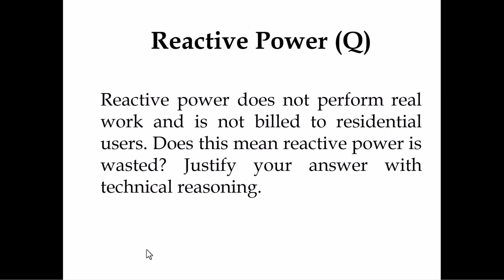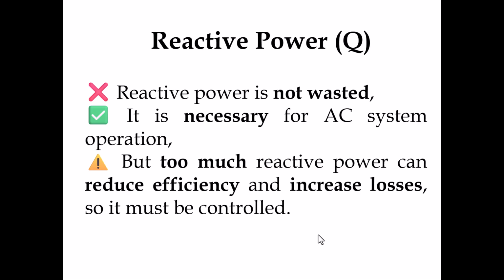Actually, reactive power is not wasted, but it must be managed. Reactive power does not result in net energy transferred to the load, as I discussed earlier. Instead, it is cyclically exchanged between the source and the reactive components of the system. In an inductive load such as motors or transformers, reactive power is used to maintain the magnetic field. In a capacitive load, it supports the charging and discharging of the electric field.